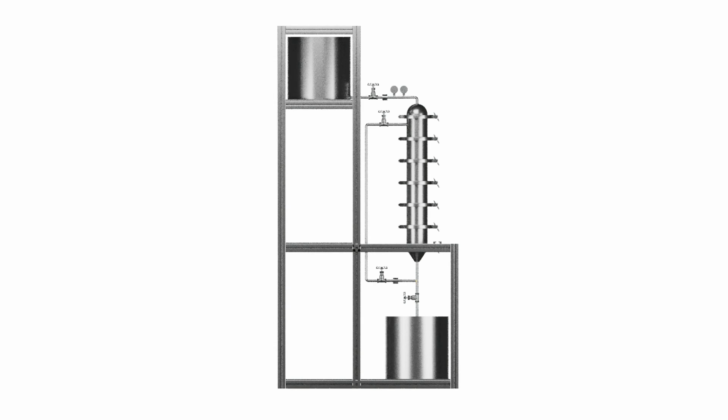Compared to conventional mitigation methods, our i-Adsorb system can remove 3-MCPD and GE efficiently without producing additional wastewater compared to traditional methods. Our self-developed i-Adsorb system utilizes chemisorption and a packed adsorption column, which is modular, small footprint, and low capital and operation expenses compared to improving existing plant layout.